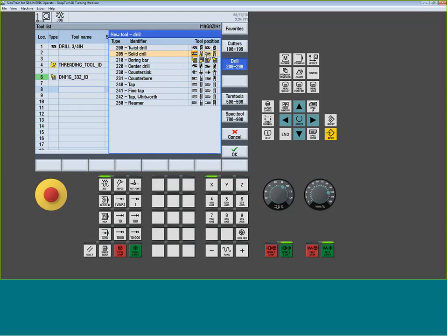And the solid drill is really supposed to kind of represent an insert drill. So the drill orientation you're going to pick when building a drill is going to be pointing the direction the drill is physically pointing. So in this case, we want pointing to the left because that's where our main spindle is. Why do we have these other drill orientations? Well, that would be for live tooling, for argument's sake, and different orientations. So the next one over would be for what we call peripheral or OD drilling. So I'm drilling on the side of my part. The other direction would usually be for machines that maybe have a main spindle, subspindle, and I'm drilling on the other side. That's certainly a way it could be denoted.